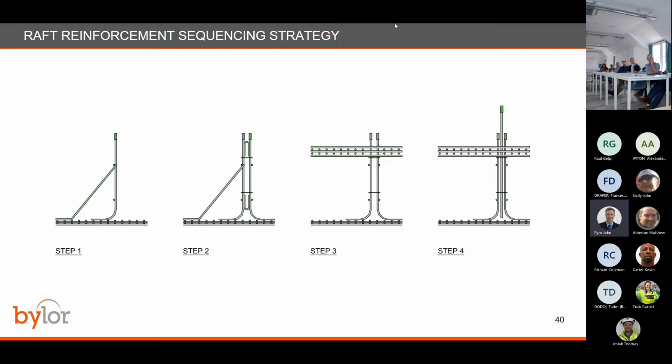We just didn't trust that at all, particularly with the radial wall, where you've got a semicircular shape and square gaps. If it goes wrong, you've got issues with covers, you might struggle to get your plates in because you've had to move some of the bars, wall junctions aren't going to work. So we completely rehashed the build sequence.